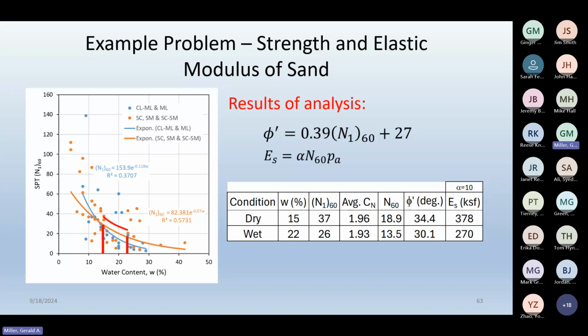You think you can develop these curves back in your own offices? Yeah, I know, it's a lot of extra time. I've been lucky to have Metco provide me a lot of data, so I've been able to develop these curves. But it is time consuming. You sit there and look at borings and pull off water contents and N values, but you probably have all that digitized. You may have it in tables somewhere. It wouldn't take long to put that data together and you can start developing some of these.